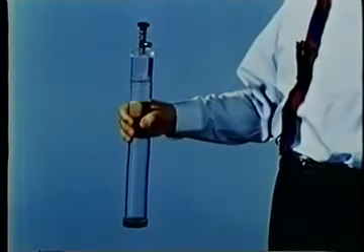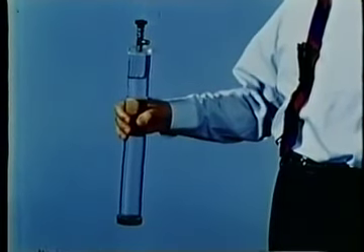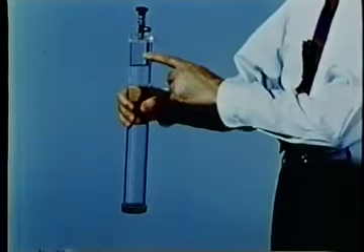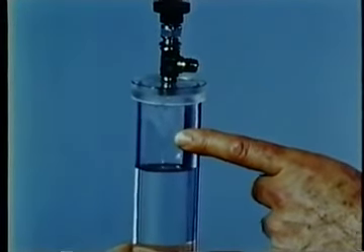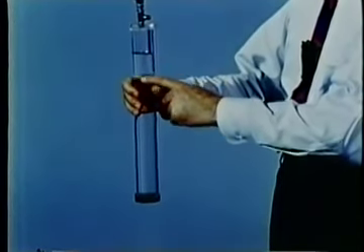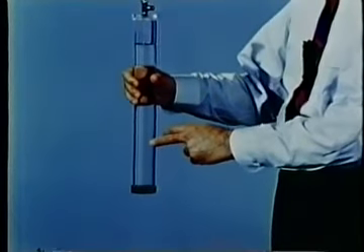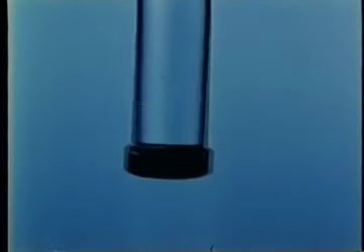Another important effect is the noise that collapsing cavitation bubbles produce. A partial vacuum has been pulled in this space above the water column. As I accelerate the tube downwards, the inertial forces produce a pressure gradient in which the pressure decreases as you go down from the free surface. At some level, the pressure is low enough for the liquid to cavitate. The noise is a result of shock waves generated upon bubble collapse. The pressures associated with collapse are high enough to cause failure of metals.